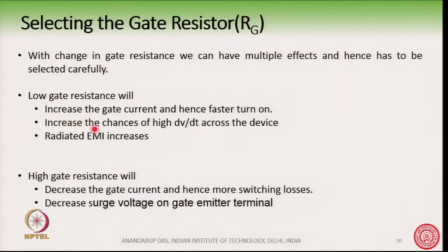Okay. But there are other issues, like if you have a low gate resistance, then it increases the chances of high dV/dt across the device.